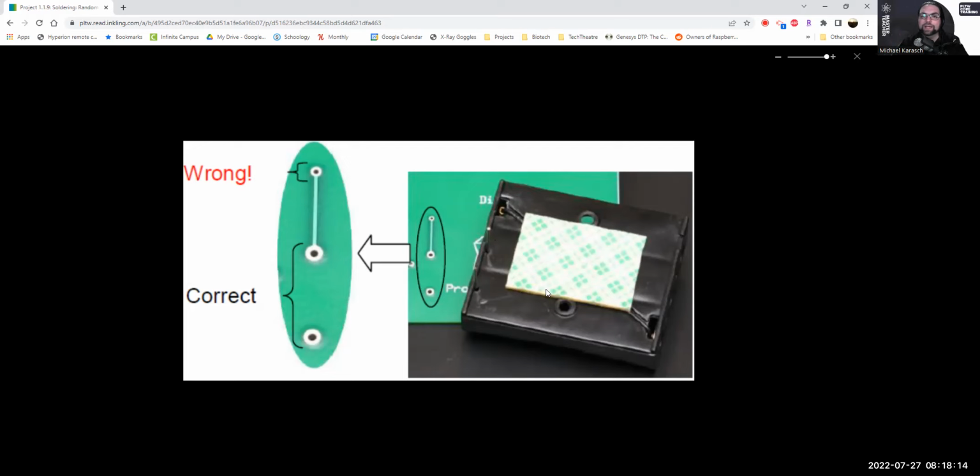And this is one of the things I look at every single time. Did they get this battery pack in the right place? If not, no batteries for you. You made a mistake, right? I'll usually check the chips, things that take me 10 seconds to look at. Are the chips in the right way? Is the battery pack in the right way? Are they missing any components? Anything like that.